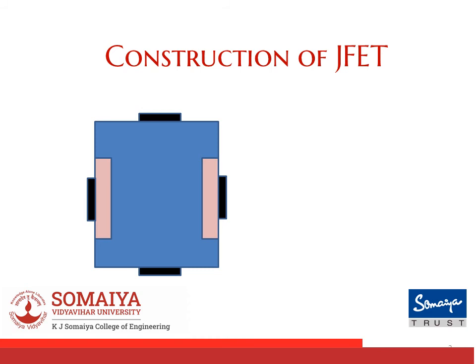Now, since they are going to be of different dopings, you will have a junction formed the moment they are connected. This is mainly due to the diffusion of charge carriers through the junction, and that is why you have a PN junction created there. This depends upon the doping densities that are present between the p-type and n-type.